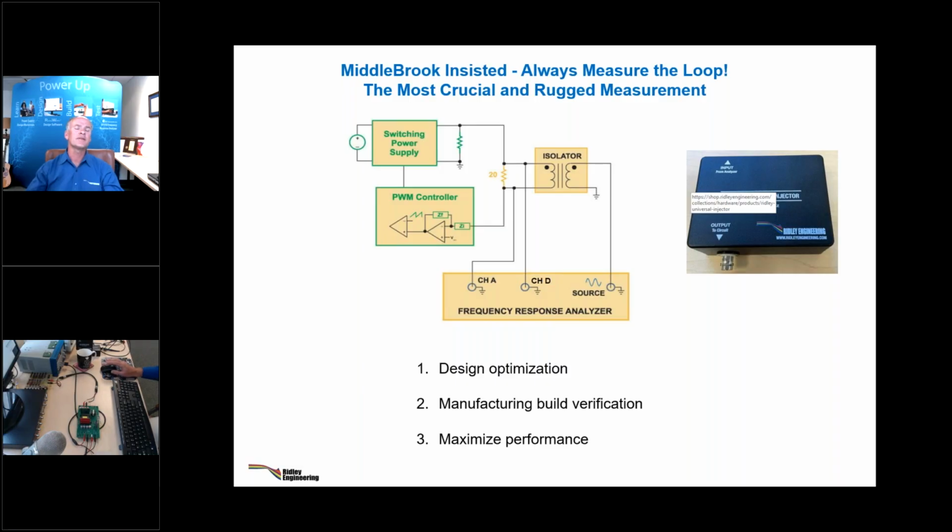No, it's actually not that. Here you're injecting a signal across the resistor, right? So you're forcing a voltage across that resistor. And at that one frequency, the loop is effectively open because there's forced to be a difference between these two. So this is how you get an open loop measurement while the loop is closed, because the signal itself opens the loop and every other frequency is closed. This can be a high bandwidth system here, but I'm breaking the loop with the signal.